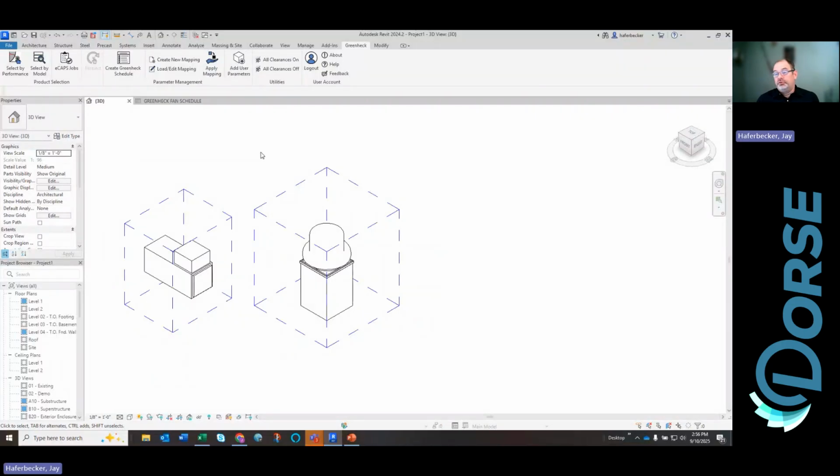Now, there are different solutions for that. I've seen people have an Excel file outside of Revit that they create, and then they import that Excel file into their shared parameters, and then that shared parameter comes into our Revit family. That's fairly common. It's another method that you can choose, but there are a lot of different buttons that have to be pressed to do it. That's just a different alternative. And you can mix and match the second and third techniques if you want as well. All right, so that's how to schedule.